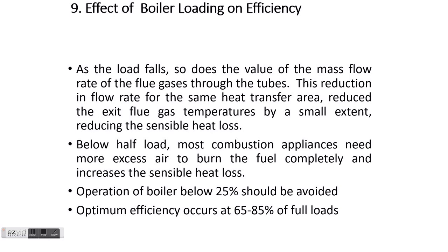9. Effect of boiler loading on efficiency. The maximum efficiency of the boiler does not occur at full load, but at about 2/3 of the full load. If the load on the boiler decreases further, efficiency also tends to decrease. At zero output, the efficiency of the boiler is 0, and any fuel fired is used only to supply the losses.